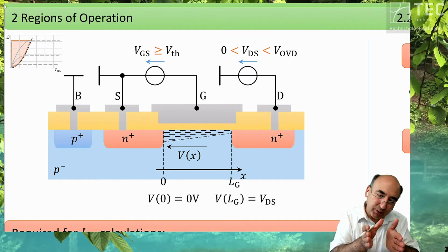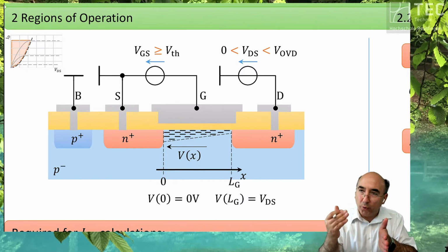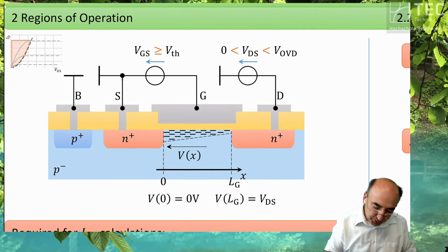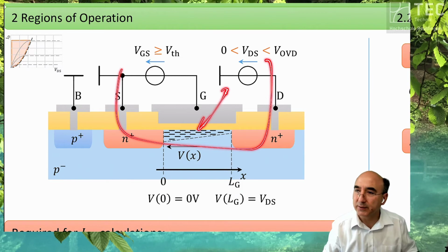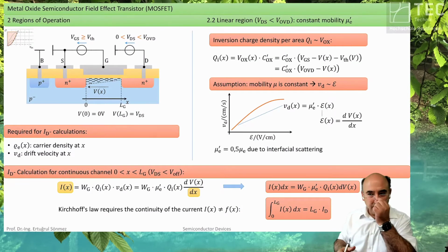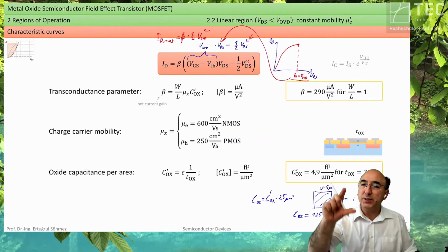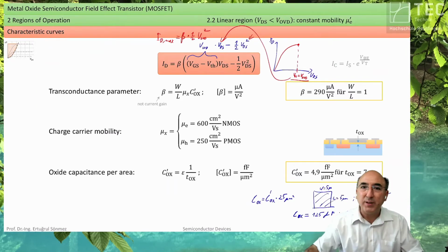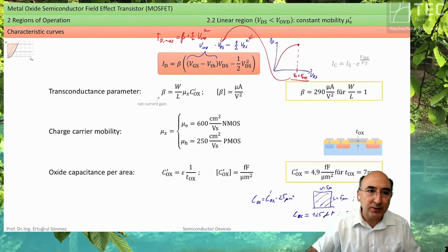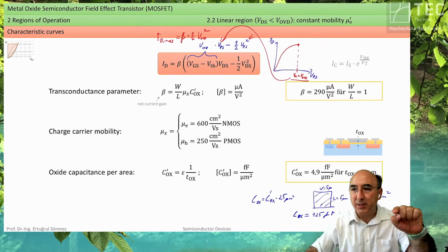So as small as you can make that stuff, as high you can get the current, or as low you can further reduce the width for a certain amount of current. Okay, so this is all the stuff the industry is working at, reducing the oxide thicknesses, reducing the minimum length in order to make transistors which are smaller and smaller for the same current.